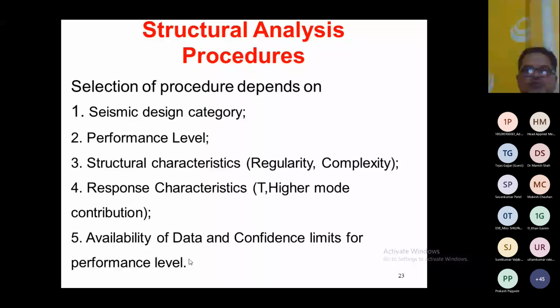So how can you select this procedure? It depends on the seismic design category, right? Now, which type of structure you are designing, right? If you are designing a very important structure, then I'm always going to go for the dynamic analysis.